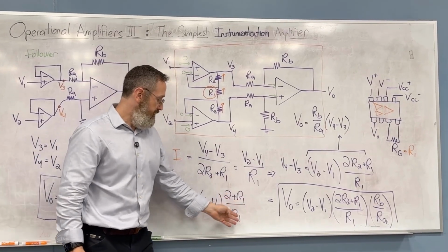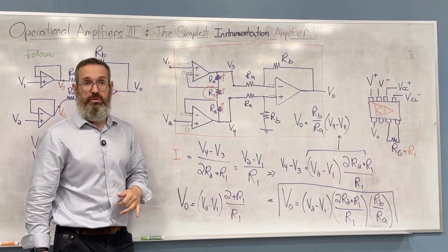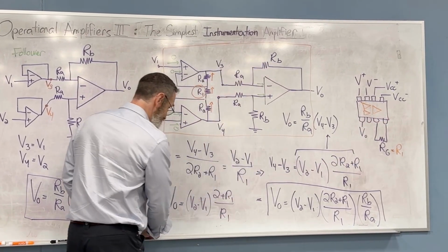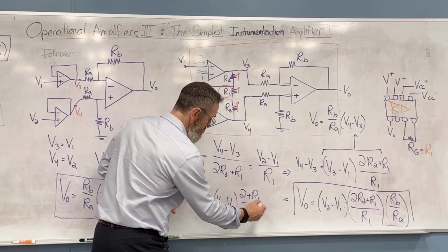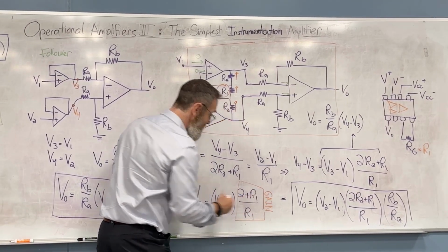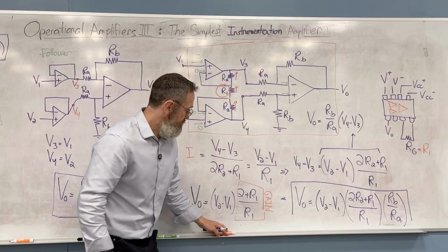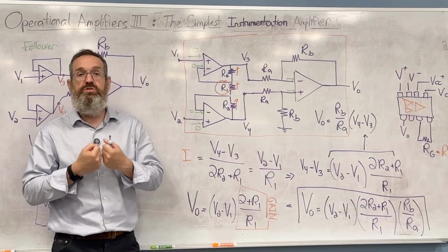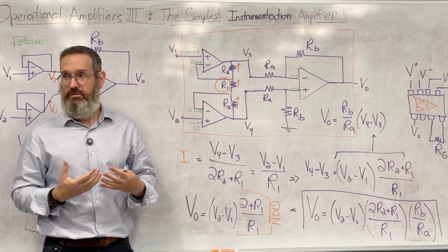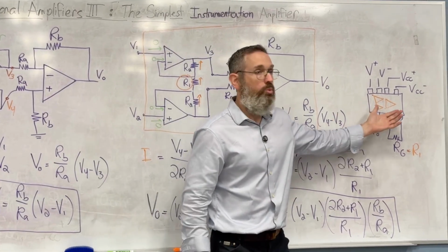If you wanted to make a circuit, for example, with a gain of 3, you would just pick R1 equal to 1 ohm. And you would insert a single resistor. In fact, any gain you want, right, this is the gain. This is the gain. Any gain you want can be obtained simply by picking a single resistor. And this is where the laziness comes in. This is the laziness. It can't be any less work.